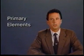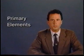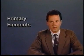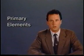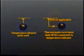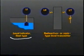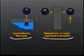Control factors that are considered to be primary elements include temperature, pressure, position, and flow. As you can see from the examples in your student guide, the symbols indicating these functional devices are very easy to understand and are very versatile. Here are symbols for a thermowell and a thermocouple, which are almost always used in temperature sensing applications. Here is a level indicator of the most basic float type and another, more sophisticated sonic type level indicator.